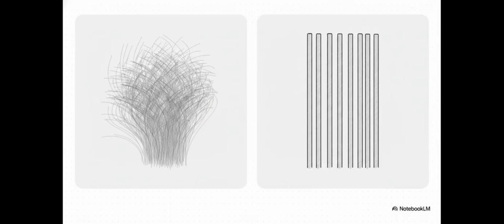Let's start with the conductor stranding itself. High flex uses ultra-fine wire strands. We're talking 36 to 40 AWG. Because they're so fine, they slide super easily against each other, making the cable incredibly pliable in your hands. But look at continuous flex.